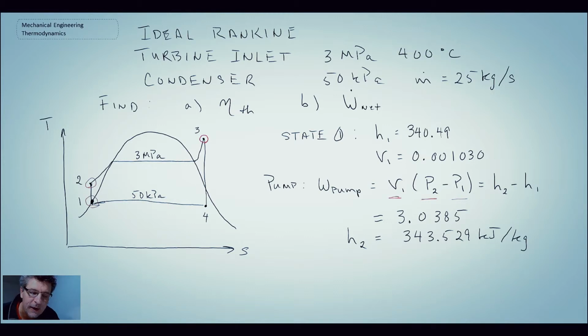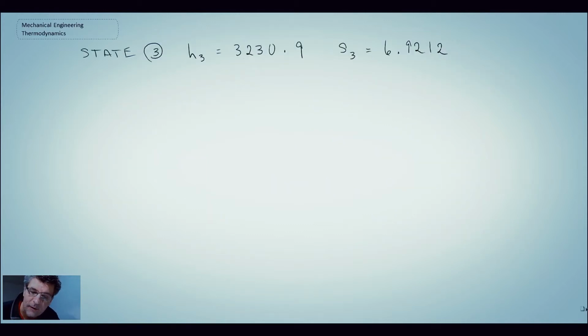It's superheated. Now we're going to use the value of enthalpy there in order to figure out where state 4 is. Right now we don't know where it is, but we know the entropy, and we can say, or assuming that this is going to be an isentropic expansion process in the turbine, we're told no different. That enables us then to get a direct link between 3 and 4, because we can write entropy at 3 is equal to entropy at 4, and knowing the pressure we can then determine state 4. So that is the next step that we will be doing here.